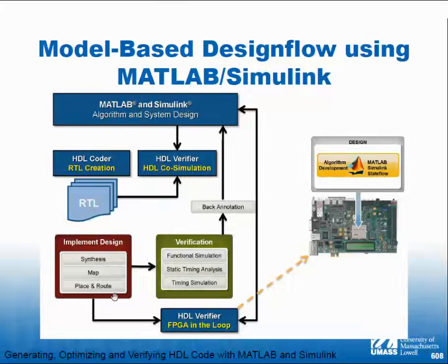We put the RTL in, then we have this co-simulation, right? We'll get to that in a second because that's down here. And then the classic path of synthesis, map, and place and route, right? Those are the FPGA design tools. And then for verification, functional simulation, static timing analysis, and timing simulation, which is what we've been talking about. So we take this stuff, we do a back annotation, we change our model potentially, and we go through this path. Now, the other thing is we can take the implemented design and put it on an actual chip.